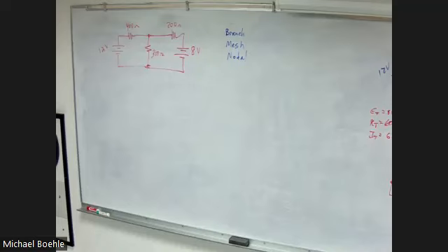So what does that mean? Well, that means that I have 4 different points, and what I do is I select one of those points as a reference. What's the voltage at that point going to be then, if I call that my reference point? 0. So I identify one of those nodes as a reference point, and then I write equations regarding the other 3 in this case. Now, that sounds like 3 equations for 3 different points. Well, you never know. It depends on what's in the circuit, and that's the fun part about this.